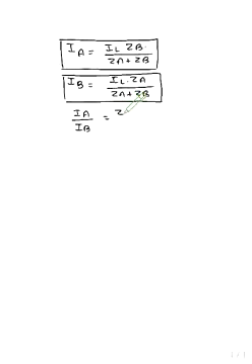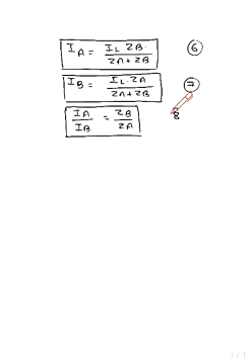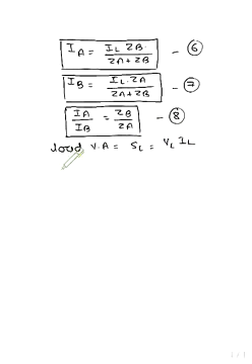So we can substitute here, and the equation will be like this: IA is equal to IL ZB divided by ZA plus ZB. This is the load current of transformer A. The sharing of the load will be IL into ZB upon ZA plus ZB.